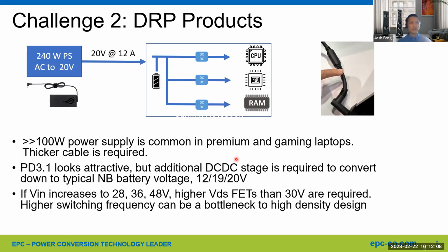So, I was at CES just this year and I've seen many really cool gaming laptops. But one thing they have in common is that they have pretty thick cables. Those cables are not a standard 5 meter cable, I believe. For example, take a 250 watt example: at 20 volt output, you will need 12 amps. Those are most likely specialized cables, and that will run higher cost and a bigger power supply brick.